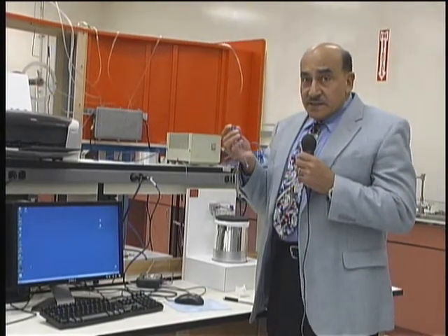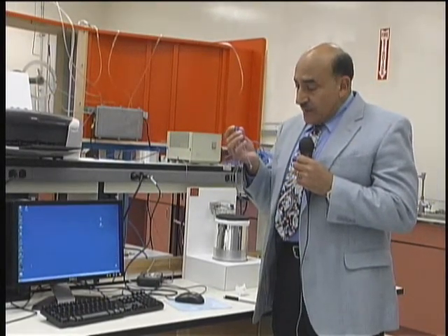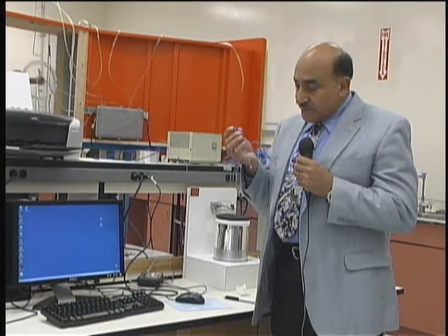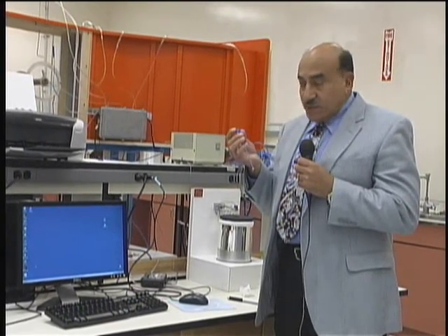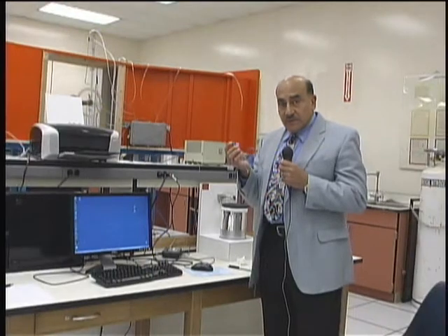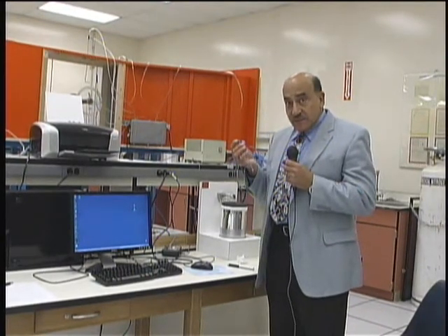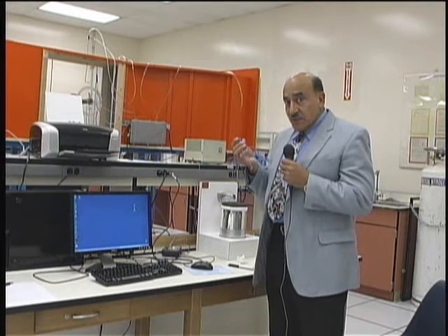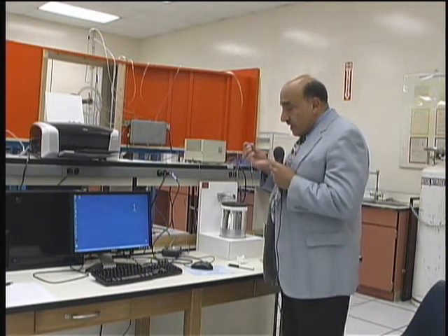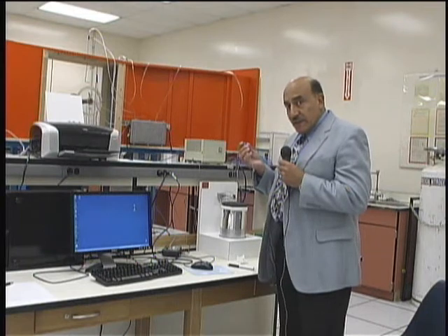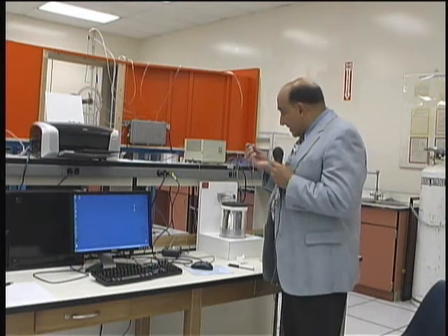And since the sphere is very small, and since it is nearly at homogeneous temperature, then we can use a lumped parameter model to say that there's no difference between the surface temperature of the sphere and the inner temperature. So whatever temperature comes out will be representative of the boiling process at the surface.